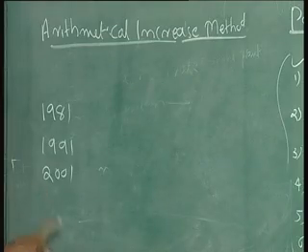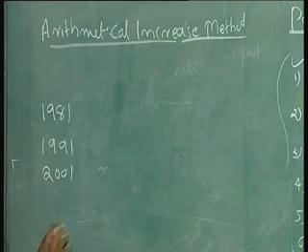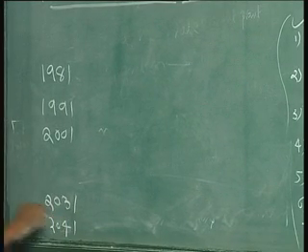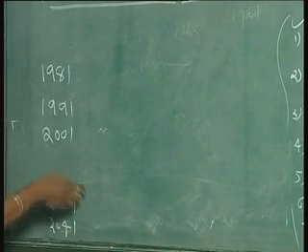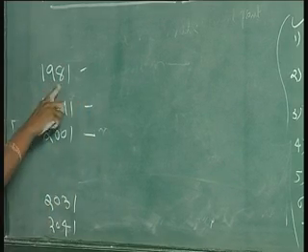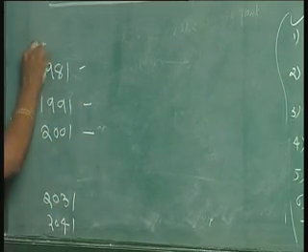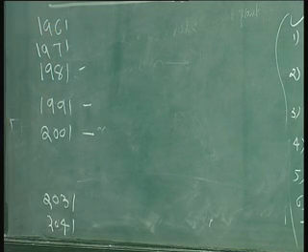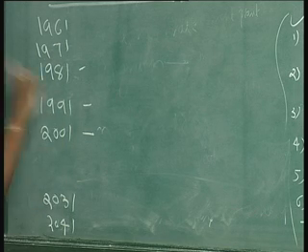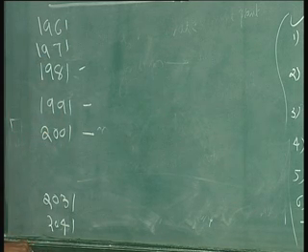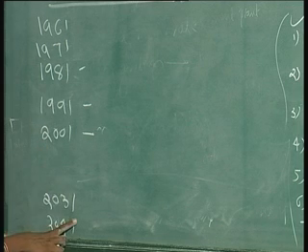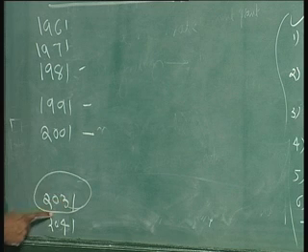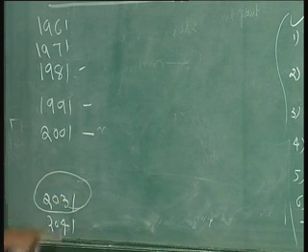So you should know what the population is either in 2031 or 2041. We have to predict this population. We have the information only up to 1981, 91, 2001, and earlier you will have 61, 71, 81, 91 etc. Based on this data we have to find out the population after the design period, because your treatment facility should be able to serve the population at that time.